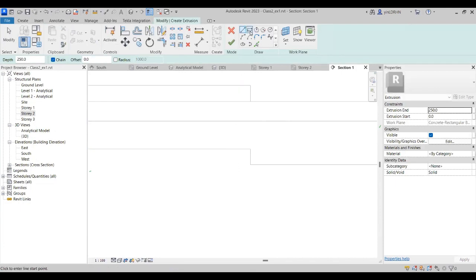Now I have the option to draw the segment, what segment I want to extrude. So I pick the point here, then here, and you can decide how much you want to go, 400, 500, let's say 400. Then you decide, finish. So now depth is how much depth you extruded. Depth is the width of my beam, 400 I extruded.